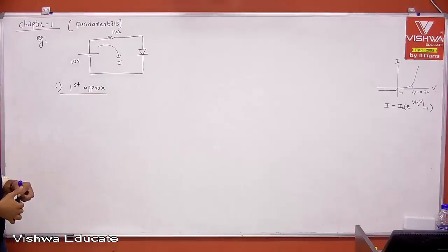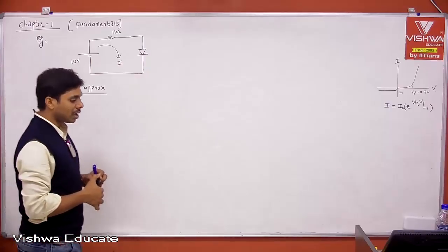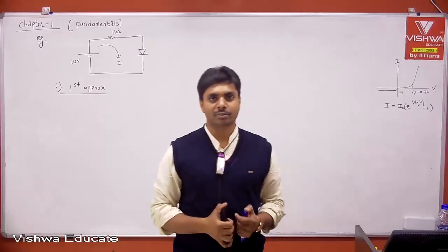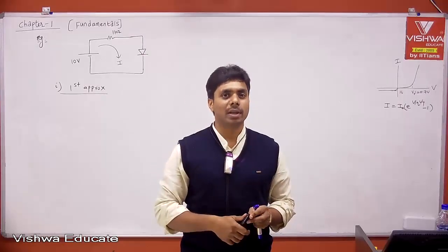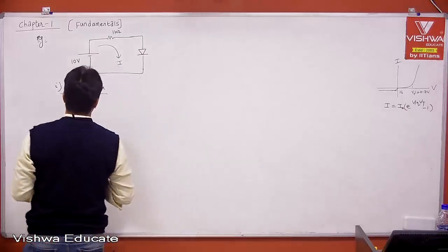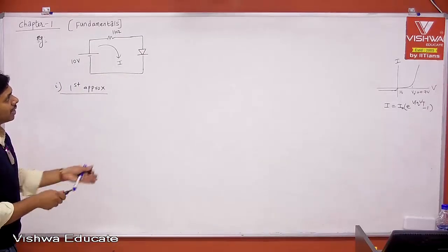Remember, if this is your circuit and you want to know whether the diode is in forward bias or reverse bias, to find the status of the diode, there is a technique. The technique is to open the diode.